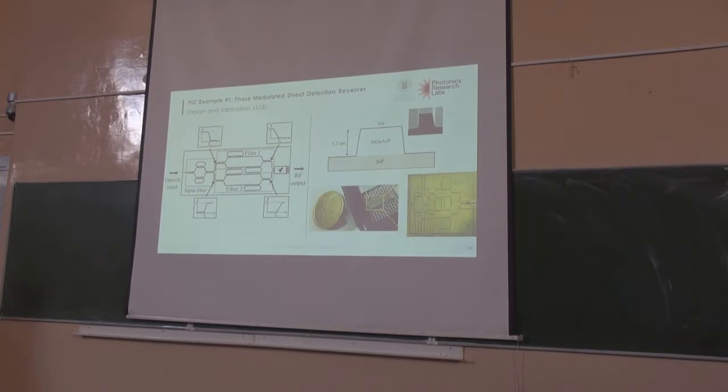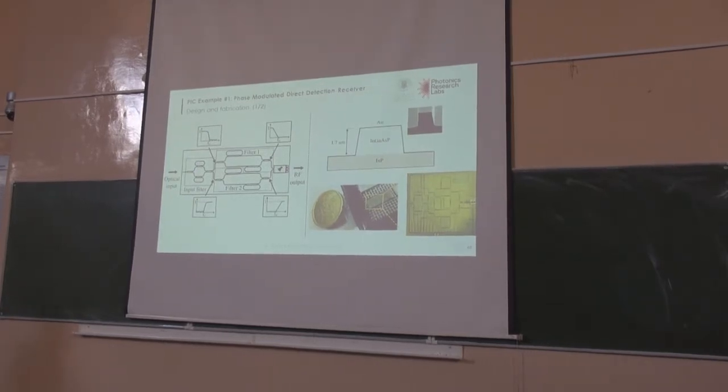Okay? So we did this on a photonic integrated circuit, and you can clearly recognize that we use the ring-assisted Mach-Zehnder architecture. You can see here the Mach-Zehnder with a ring in the arm, one filter, and then a second filter stage, one filter again here with a Mach-Zehnder with rings, and another one with Mach-Zehnder with rings.